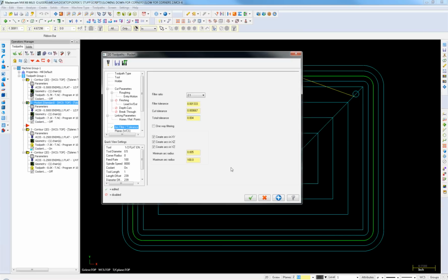Right. Yes, I've actually had extremely good luck with Mastercam and filtering. I've been using the software since the beginning of version 8, and I've just never had a problem with it filtering. Agreed. So I would say feel free to filter away. I have it set up in my defaults, where my filter's turned on 2:1 at 1,000th on every toolpath, all the 2D toolpaths. Okay, well, Mike, I'm going to have to call you on that.